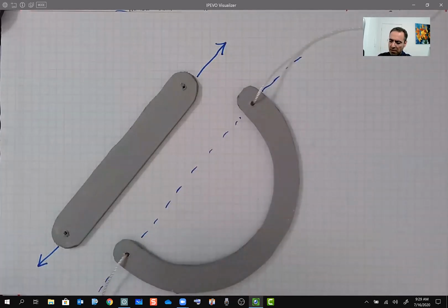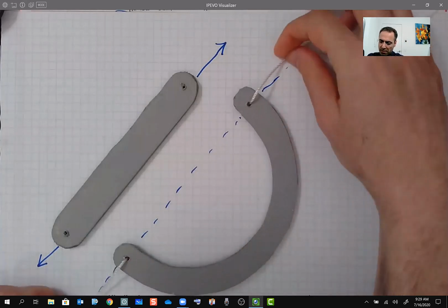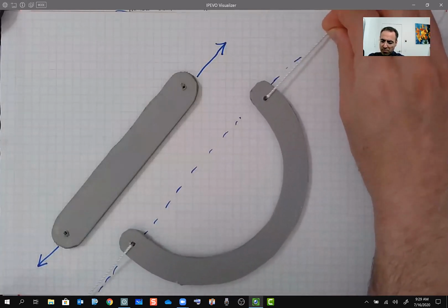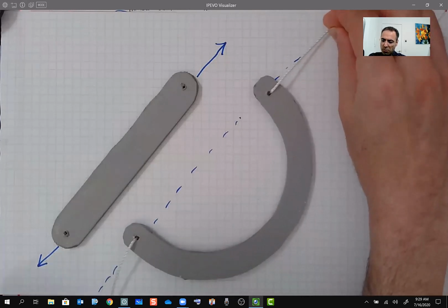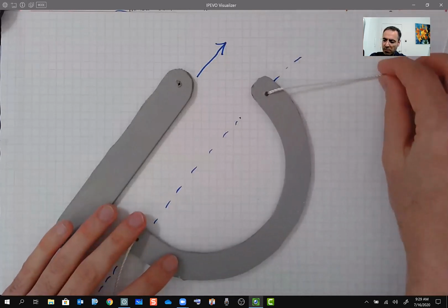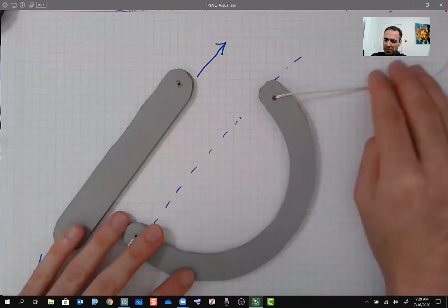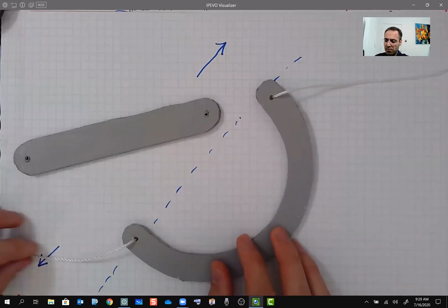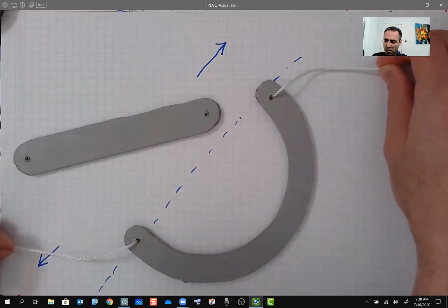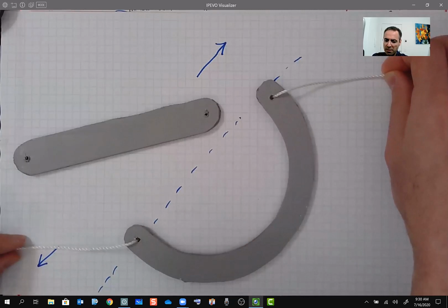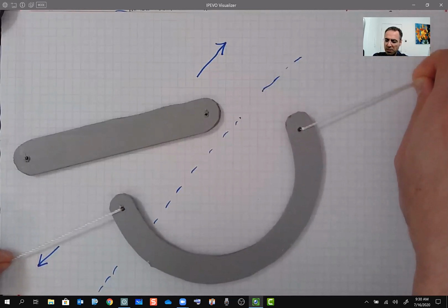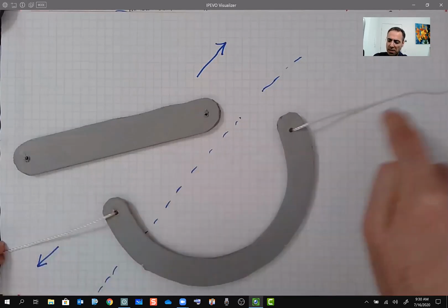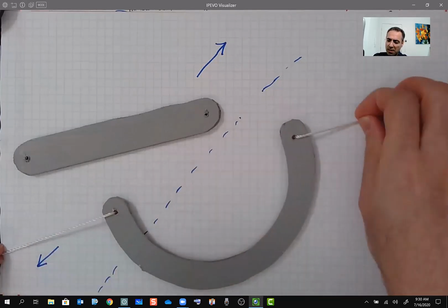So for a cable, I apply a tension, and this tension has to be in this line. You may say, no, I can apply a load like this line, then apply the other load like that one. Let's try that. Somebody try to apply load in these two directions. If I apply the loads, what will happen? You see these things rotate and balance along these lines. So always the reaction is along this line, right?